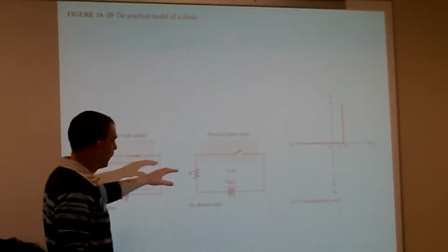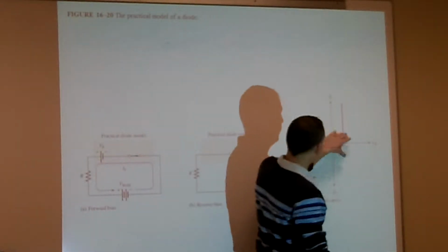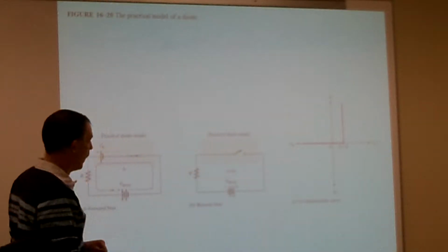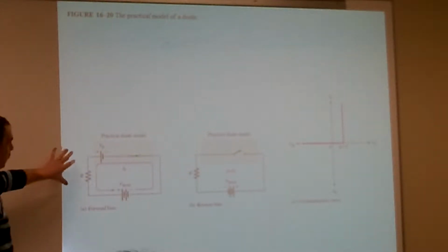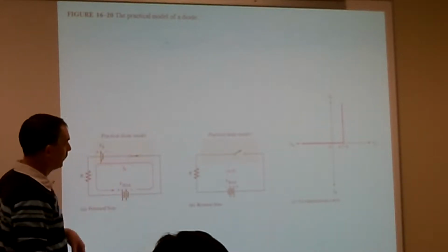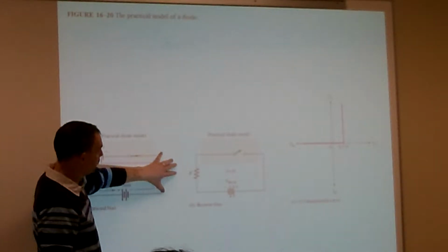so here's what our test circuit's going to look like. We're going to be putting this onto our MyDAC, and we're going to be able to plot out our characteristics curve for our diode. When we hook it up, it's called a two-wire characteristics curve, meaning we can do any two-wire component.